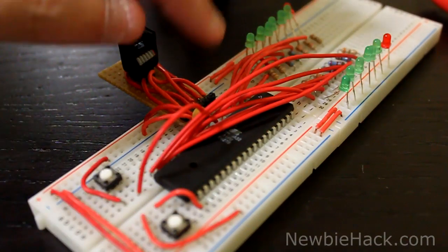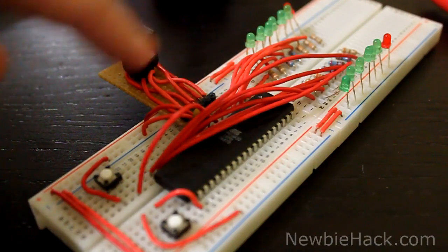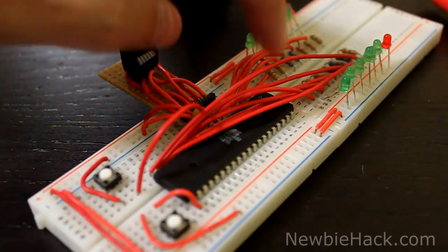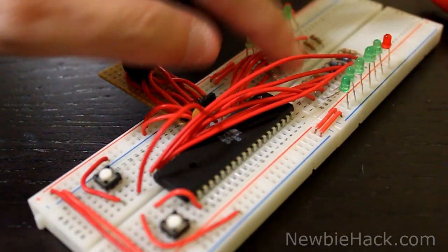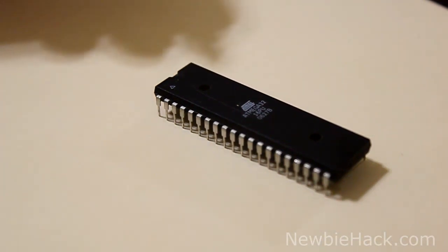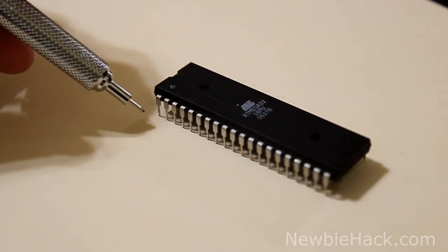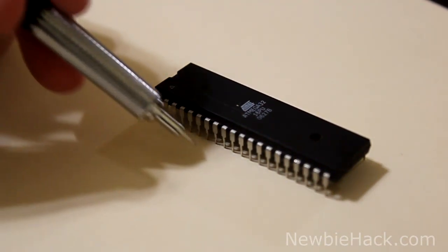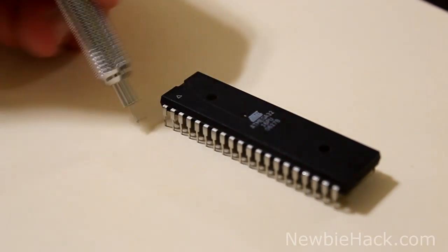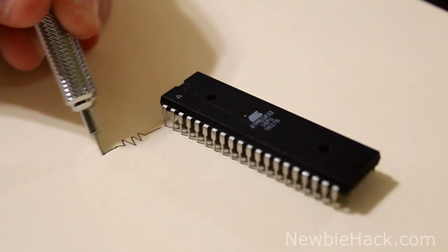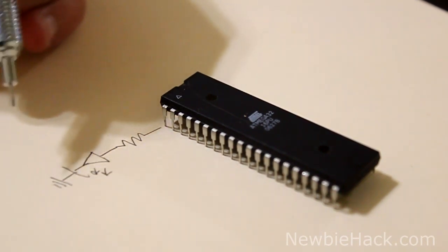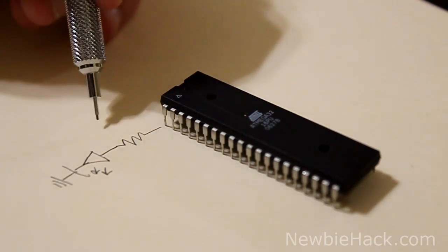Two buttons. We'll be using two ports, port B and port D, a row of LEDs that has a row of resistors, and another row of LEDs that has a row of resistors. I'm not really introducing anything new here in this circuit, but I'm going to draw it out anyway. We're going to have 7 LEDs with 7 resistors, and we're going to have a button on port B. And these resistors are going to be the same as before, 330 ohms.